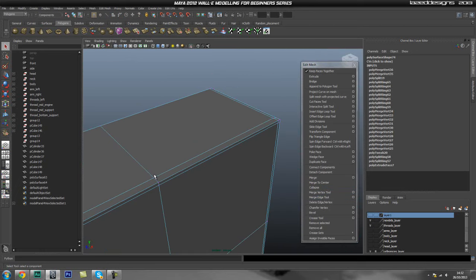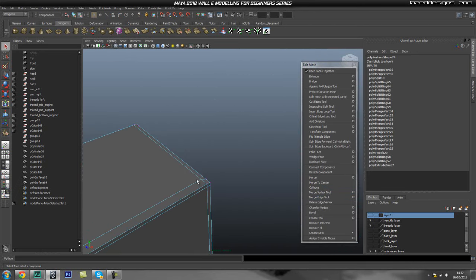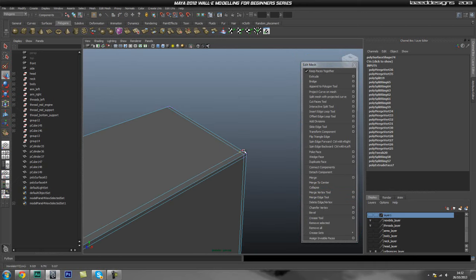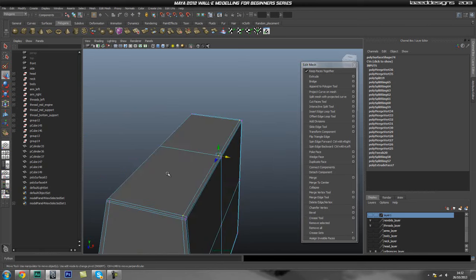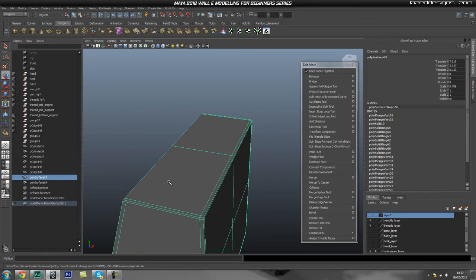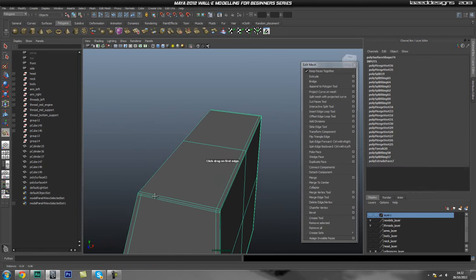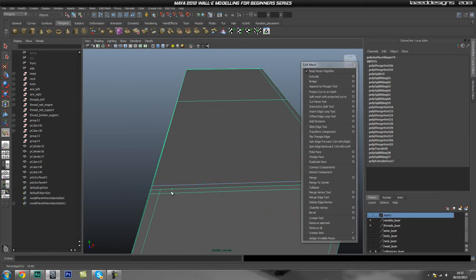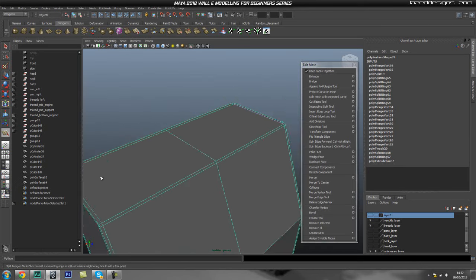Okay, and I'll also just select these verts and move them on this axis to snap it to this one. Great. Let's go ahead and do that again on the other side. So object mode, shift right click, split, and split polygon tool. And again, click and drag. And for some reason it doesn't snap to our vertex. It should do, but it's fine.